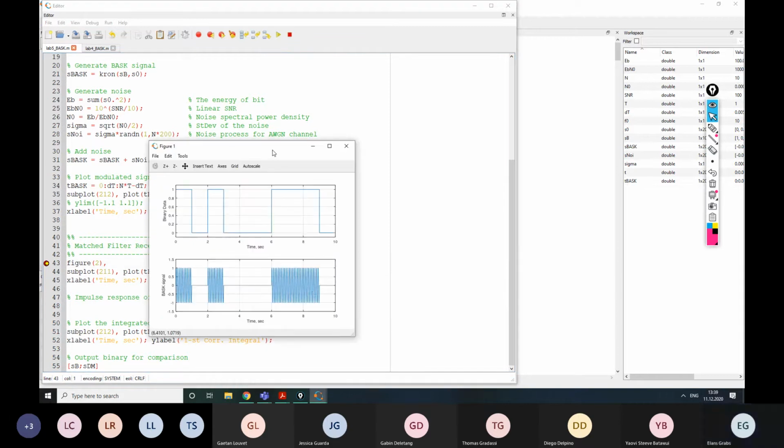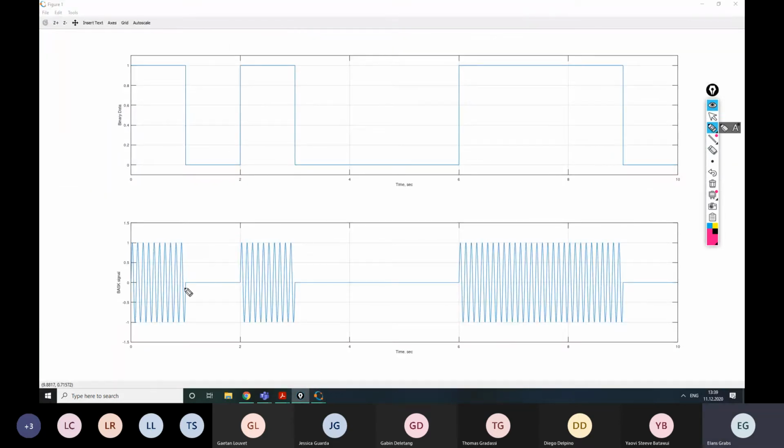So, this S0 signal is actually the contents of one symbol, right? So this is this harmonic signal part, and this one, and here it is again 3 times in a row. So we need to actually have it inverted in time. So basically we need to flip. So this is going to be the beginning of our signal, and this is going to be the end.